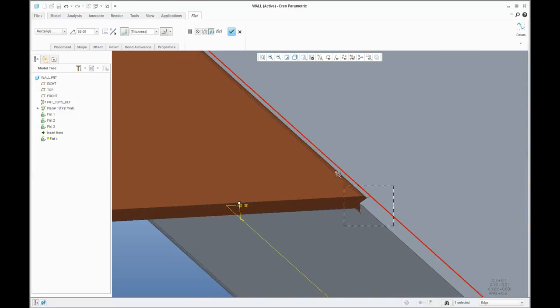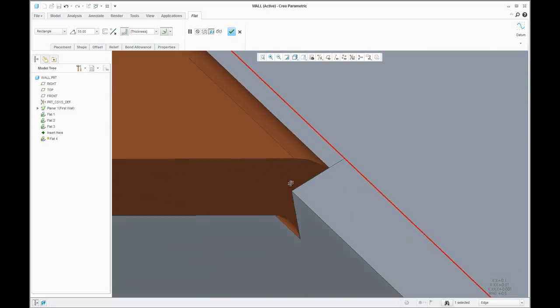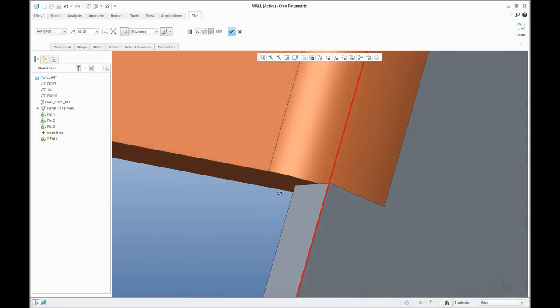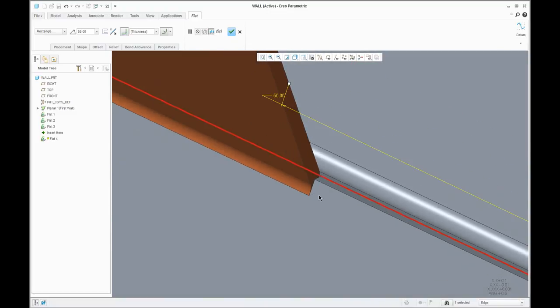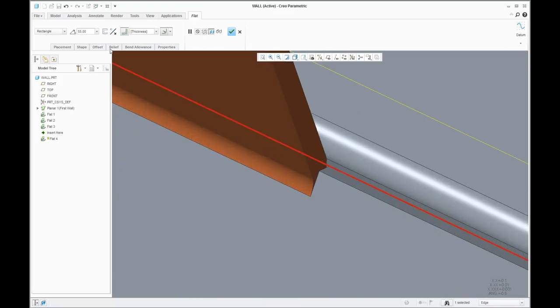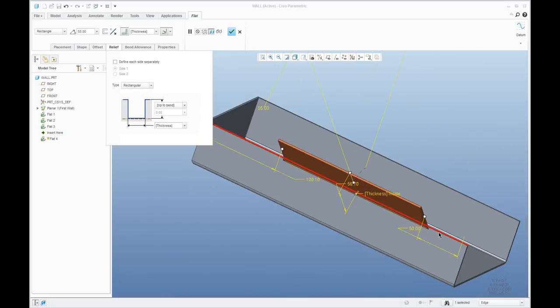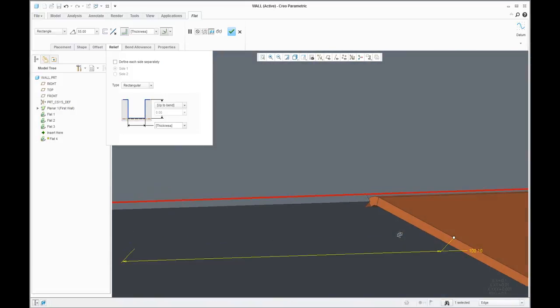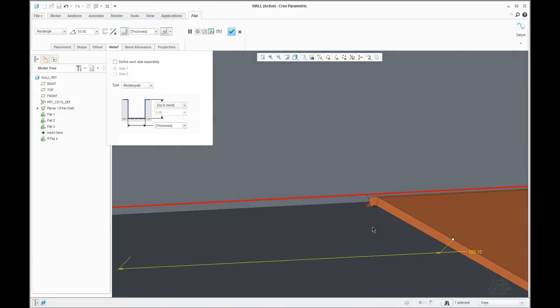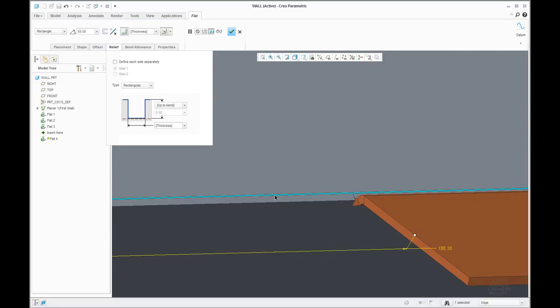And relief. You can see here that in my configuration it is set that if you create relief, set rip. Or you can manually change it, for example, to stretch, and the dynamic preview will show you how it looks. There are a lot of different kinds of rips, and the system will create a rip on both sides, on the left side and the right side.